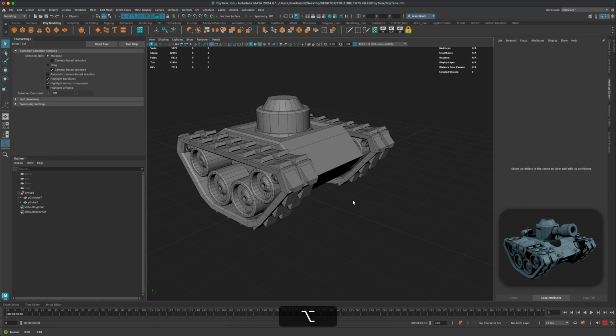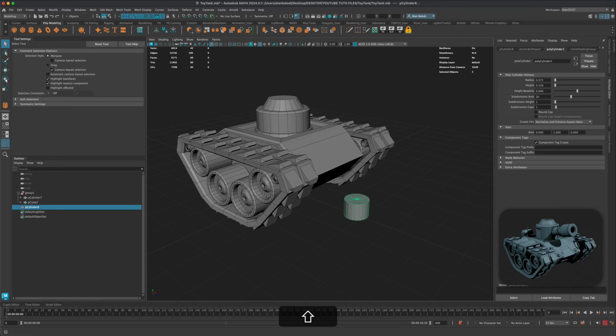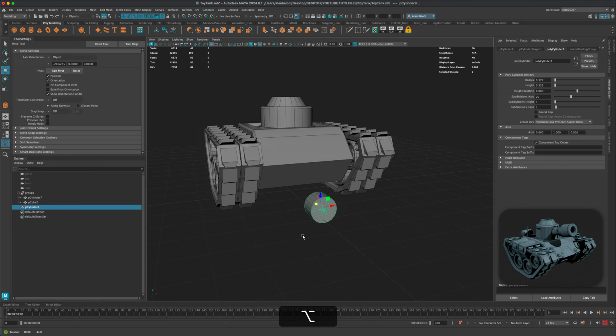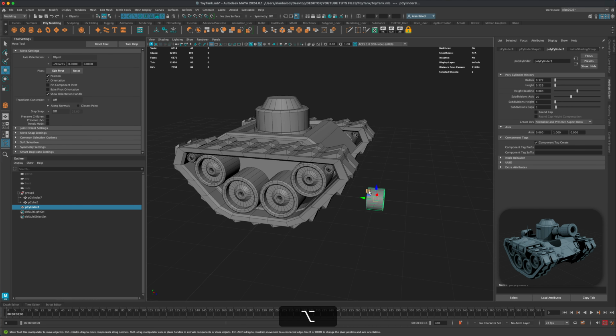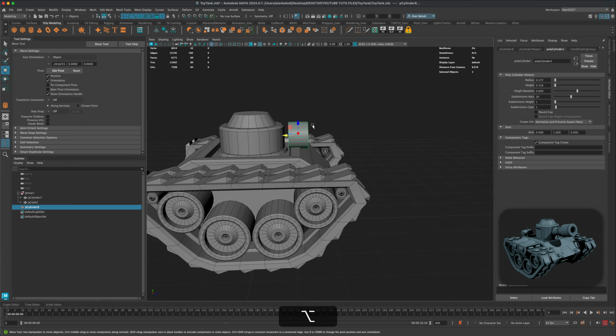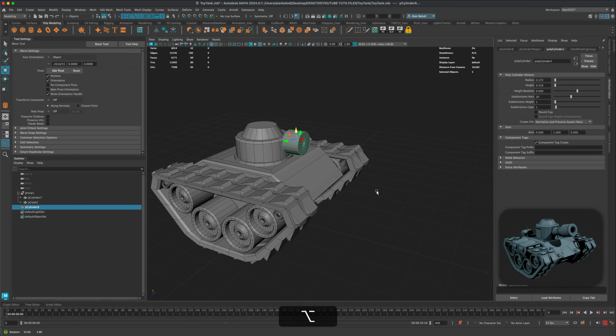All right, next let's build the barrel. So I'm just gonna drag a cylinder, and holding down the J key, I'm gonna rotate this 90 degrees. Holding down the X key, we can make sure that it's centered, right? And we can also put it in position. And now this is the part, I think, where I'm gonna be readjusting the base even more.